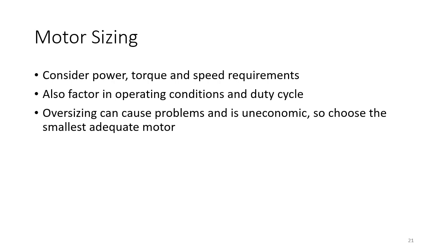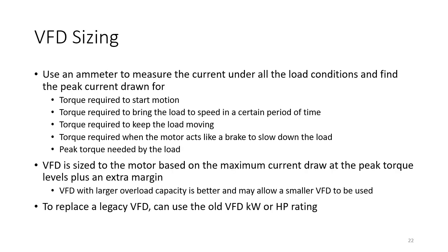Now, once you know how big your motor is, you can either use an ammeter or some sort of modeling techniques, and you could measure the load current under all the different load conditions to find out the peak current that's drawn. What you need to know is the torque required to start motion. Again, that's going to vary depending on what the load is. You need the torque required to bring the load to a speed in a certain amount of time. So how long does it take to ramp up?